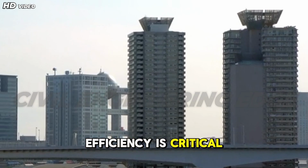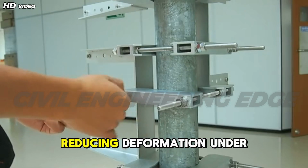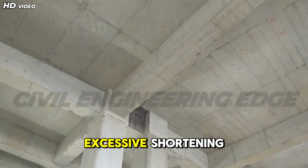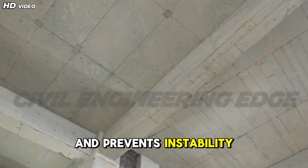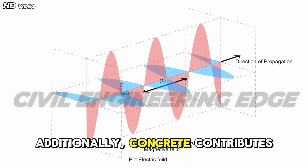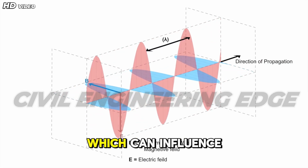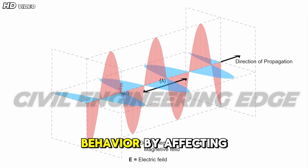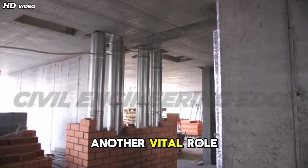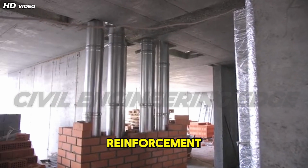Concrete also provides stiffness to columns, reducing deformation under load. This stiffness helps control excessive shortening and prevents instability, especially in short columns. Additionally, concrete contributes to the overall mass of the structure, which can influence seismic behavior by affecting natural periods and damping. Another vital role of concrete is protecting the embedded steel reinforcement.